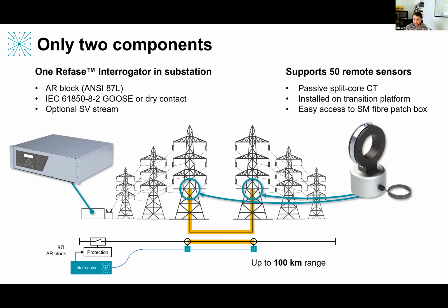And therefore, back at the substation, which is potentially a great distance away, we can give a very reliable indication to the rest of the protection and control systems about whether or not to reclose, depending on whether the fault's on a cable or overhead line section. So for me, it's a very simple, unambiguous indication, which the existing protection systems can readily make use of.